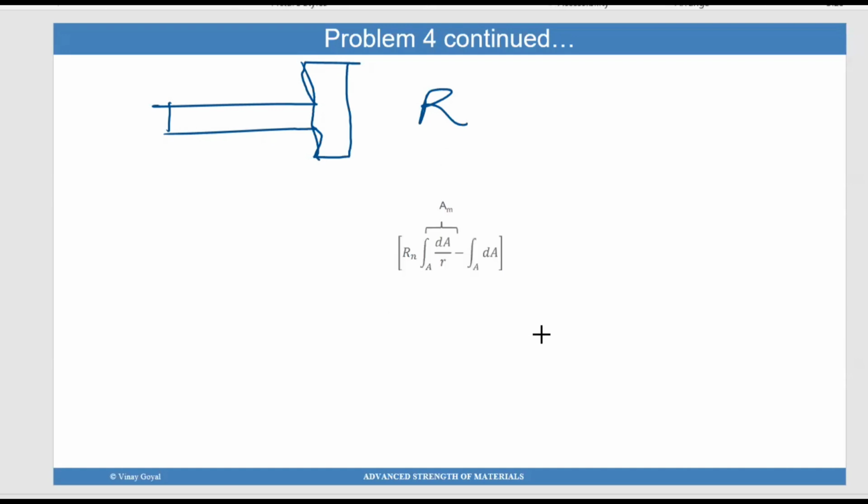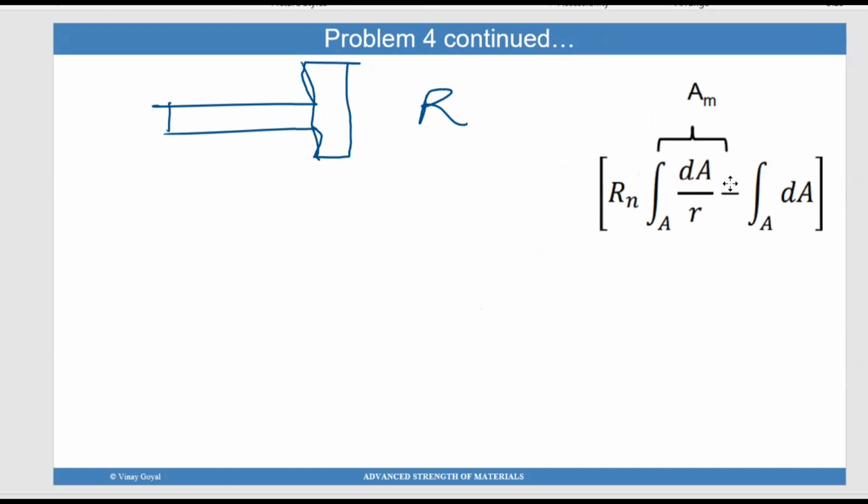So you solve this equation, which, if you go through the lectures, comes from the fact that no hoop stress exists in the absence of N. So if there is no N, like there is no axial force, there'll be no hoop stress. That is where the neutral axis comes from. If you look at the derivation of it, you'll find there is a formula which gives you the neutral axis location. And that is the exact formula that we are going to use to solve for the neutral axis.